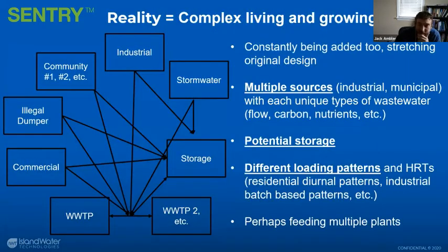What we find is it's actually a complex, living and growing entity. It's constantly being added to, stretching the original design or changing the original design parameters. You're looking at a lot of different sources. You have industrial, you might have multiple communities, you may have intentional or unintentional illegal dumpers, you're going to have commercial in there, and you're obviously going to have stormwater impact, I&I type of impact.